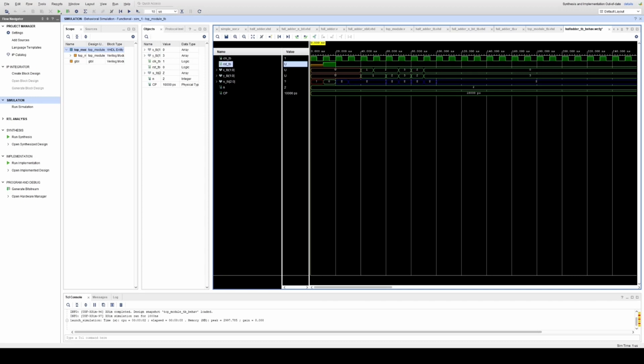So in the final design or top module, if we observe clock cycle 1 and 2, we get an output of 0 and invalid, which is the blue ones you see here. Also, the sum of x and y always shows up 1 clock cycle later. Now, I believe the reason why this is happening is due to something called propagation delay and timing issues. Since our code is all concurrent, it all runs at the same time. Each signal might have a future value, causing the results to be delayed by 1 or 2 clock cycles.